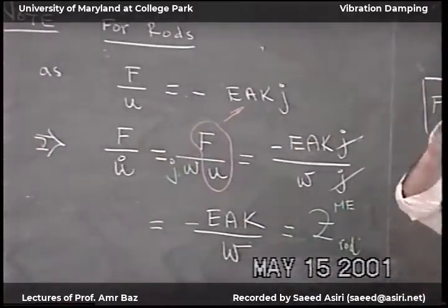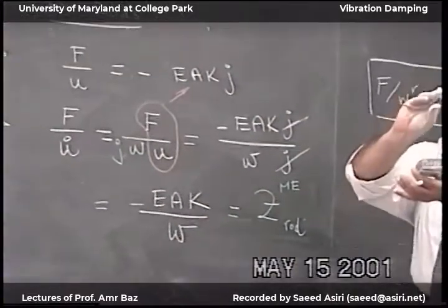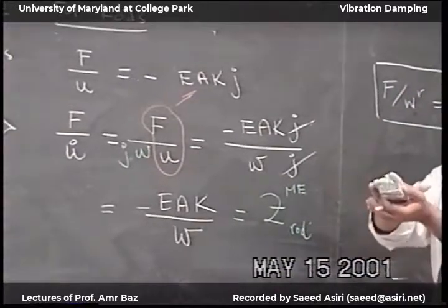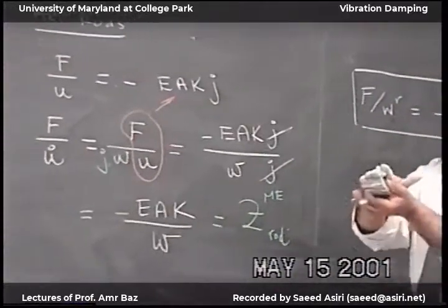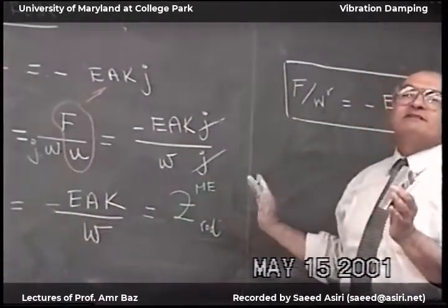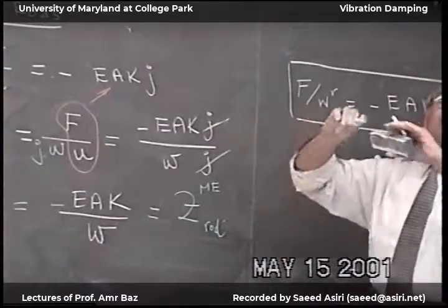Now if this rod has piezoelectric and I'm shunting the piezoelectric, then this piezoelectric has another mechanical impedance. Now these two are bonded together. The total impedance of the assembly is just the sum of these two impedances. So all what we will do now is look at a plain rod with steps.